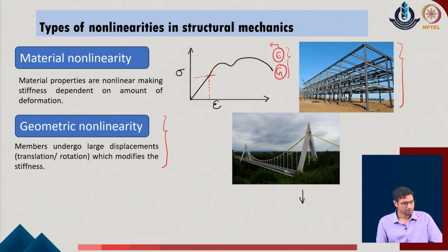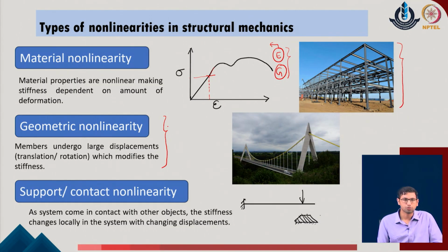As a third part, we can also note that in multiple situations where large deformations are possible in the system, those are the flexible structures like the regular cable based members, the members which are very thin or slender, the members which are subjected to loads which are compressive in nature. Typically those members have the standard behavior where the deformations can exceed the standard small deformation levels, and in those situations the user has to consider the change in the stiffness due to these increased levels of displacements of the given system.